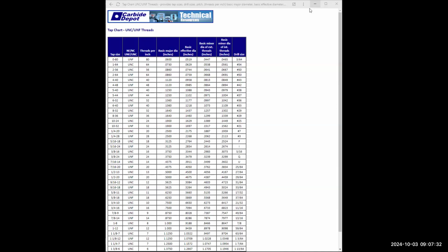And I'm going to offset this line downward, enter. I'm going to stretch this line to about right there, enter. Now I'm going to do my trim here, here, here, here, enter.